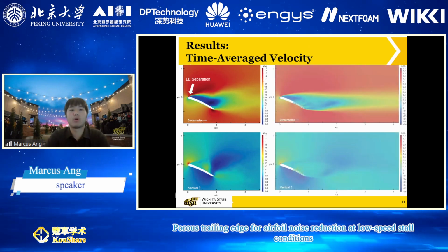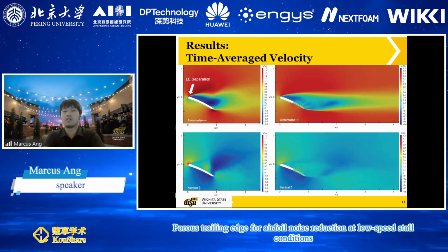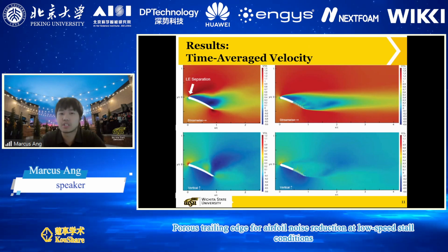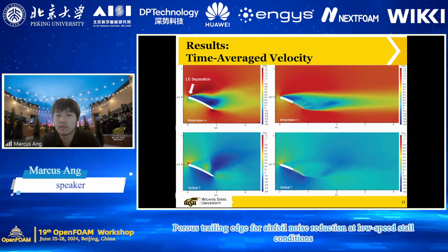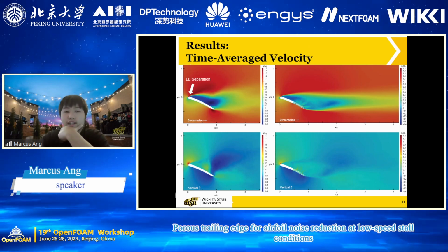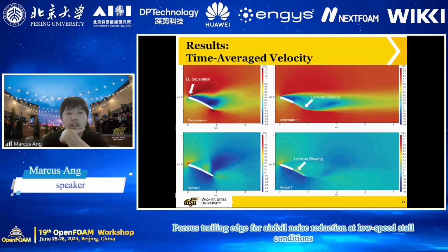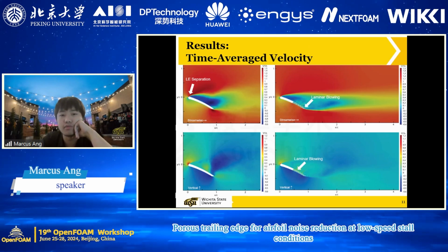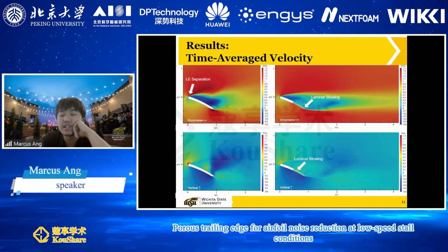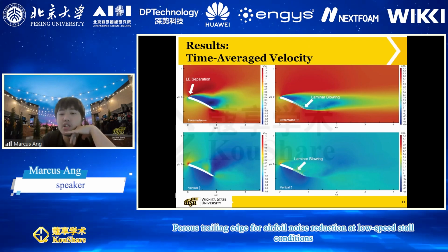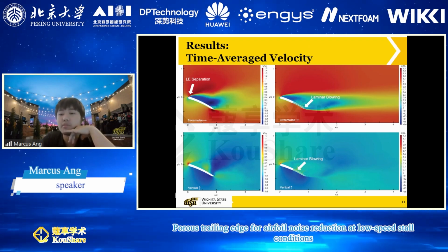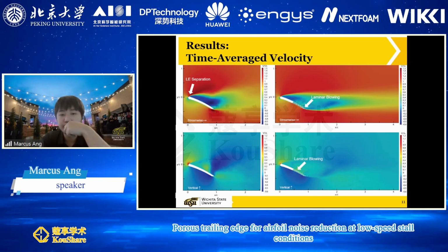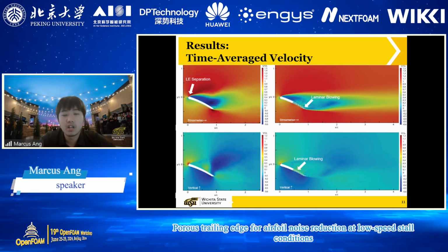When we compare it with the porous case, you see some very interesting behavior. At the leading edge, you actually get very similar separation behavior. You only get some differences towards the mid-chord, the trailing edge and the wake area. Now, if we look closely at the vertical component, the bottom right, we can see strands or jets of momentum, and that's actually blowing, and we'll see that it's laminar in nature. Essentially what it does is it injects momentum from the pressure side to the suction side. This can also be seen in the streamwise direction.